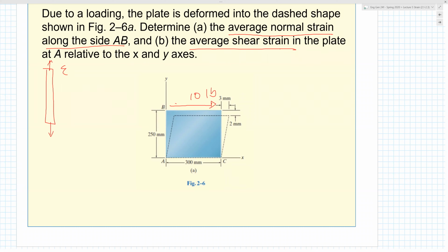So remember, there's a reason why I drew that box and I drew a line, right? What happens to that line, or even if it's on the potato, what happens to that line before and after, due to normal forces, right? Or due to anything. And then the next thing is, what happens to the rotation? What is the angle? So different points, as you saw, can strain differently. And what I mean by strain is both shear and normal, right?